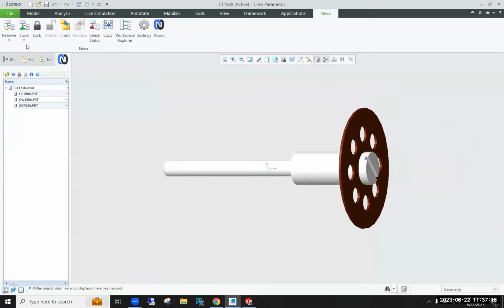All right. Now I'll store this hierarchy. So the bill of material, I'll export it. So this assembly and 3 subcomponents. To do that, we just go to this button right here and export BOM. It'll put a file in our work folder, which I'll show the import tool later. It's a single web page, and you can import multiple BOMs and all that good stuff. But for right now, I'll switch over to SolidWorks and show SolidWorks as well.